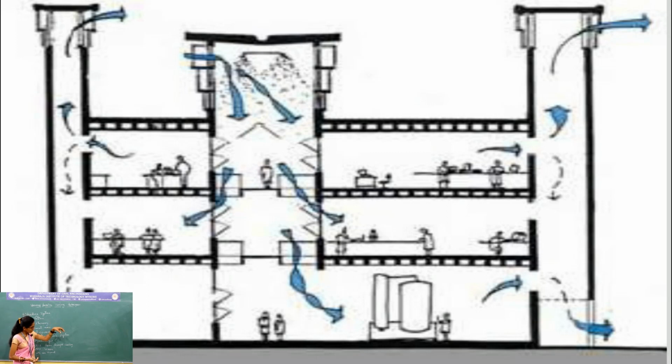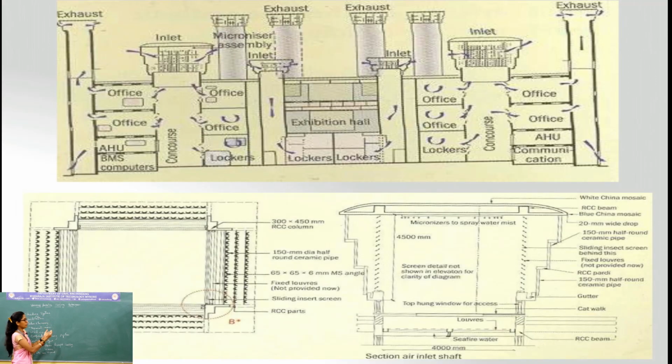So what is happening, it is going to sink, and from the other two towers, which are at a bit greater elevation and constructed in such a way that a good amount of air can escape, a good thermal buoyancy can be generated in a building. So that air is getting raised up and vacated.